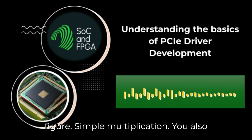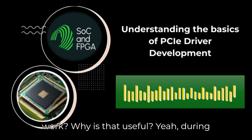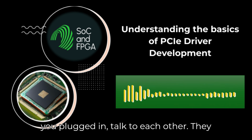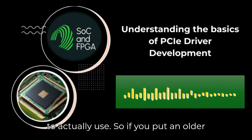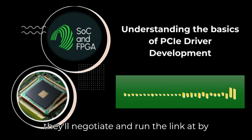Simple multiplication. You also said the number of lanes used gets negotiated automatically. How does that work? Why is that useful? Yeah, during startup, what's called link training, the hardware on both ends of the connection, like the motherboard slot and the card you plugged in, talk to each other. They figure out the maximum number of lanes they both support and agree on how many to actually use. So if you put an older x8 card in a newer x16 slot, they'll negotiate and run the link at x8 speed.